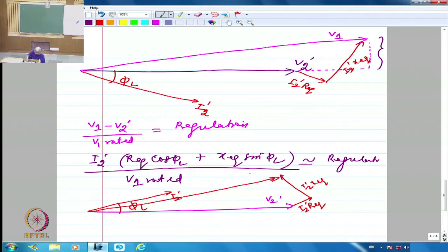This is what is going to be my final value of V1. And you can see that V1 and V2 dash are almost of comparable length. In fact, if you had had X to be more inwards, then your V1 would have been smaller in all probability than even V2 dash, which means the applied voltage happens to be smaller, or slightly less, as compared to what you get on the secondary side.